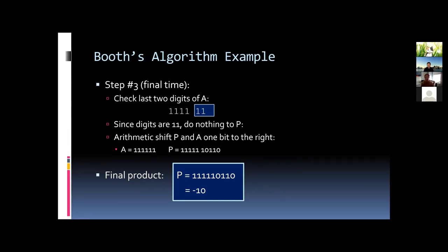I understand that it doesn't look simple at all, right? But from the hardware perspective, that's very simple, because the only thing I do is compare 2 bits at a time. I never look at more than 2 bits, and remember this thing can be 32 bits. Right now, as a human, it looks simple to you, I picked simple numbers. But imagine that would be 32 or 64-bit numbers. That's going to be a really long number, so good luck multiplying it by hand. But this is a very easy algorithm. It requires very little hardware. I just need to look at these bits and barrel shift, like I need to shift everything to the right. And that's pretty much how the Booth algorithm works.